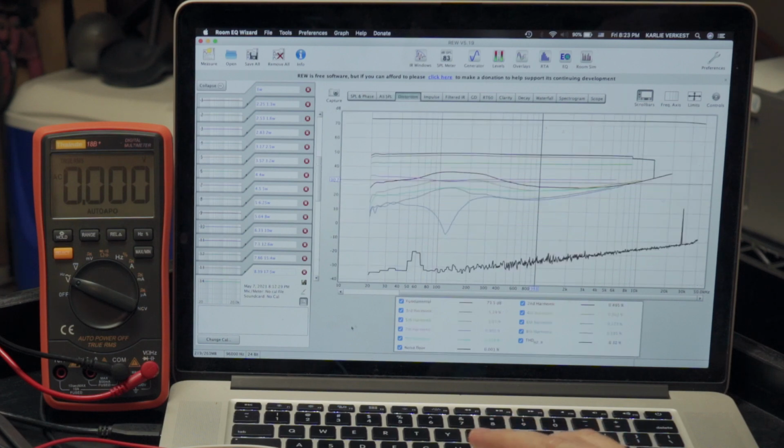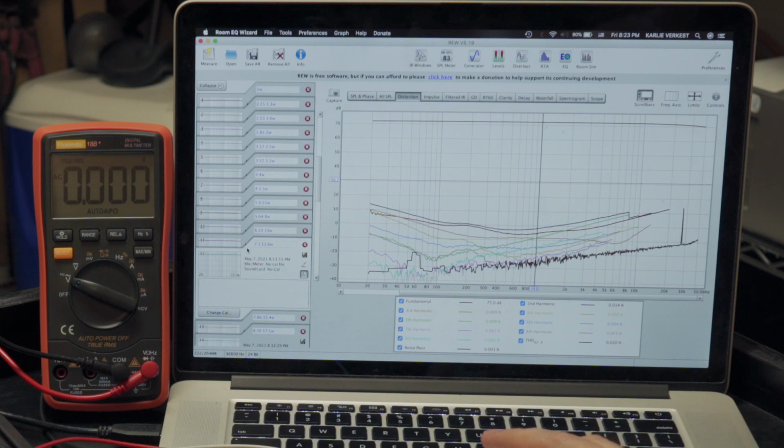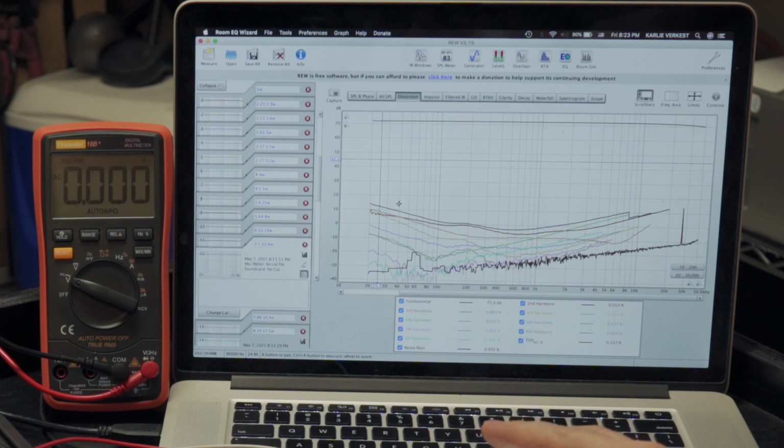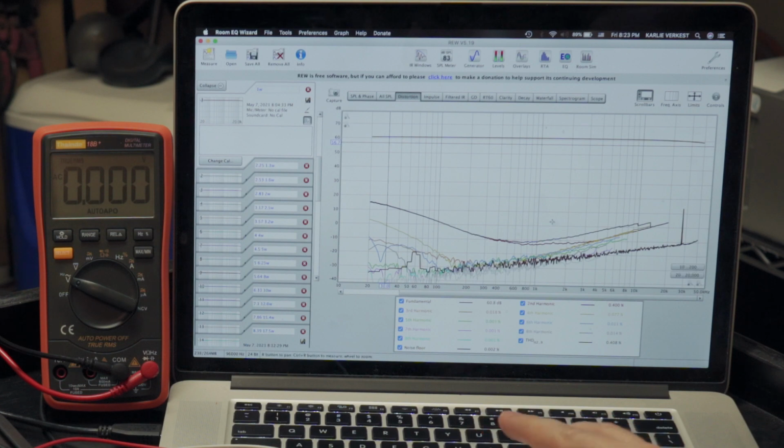All right, so you can see our noise floor. Now our signal to noise obviously is going to get better and better the louder we get here. So let's go back to our last unclipped one here. And our distortion is still very nice. In fact, interestingly, the percentage of distortion per signal goes down with this amplifier as power increases up until the point that it clips, right? Let's look down here, for instance, at 30 hertz. Here we have a total distortion of 0.09% at 30 hertz, but you'll remember 1 watt at 30 hertz was 0.4%. So that's a lot of difference there.